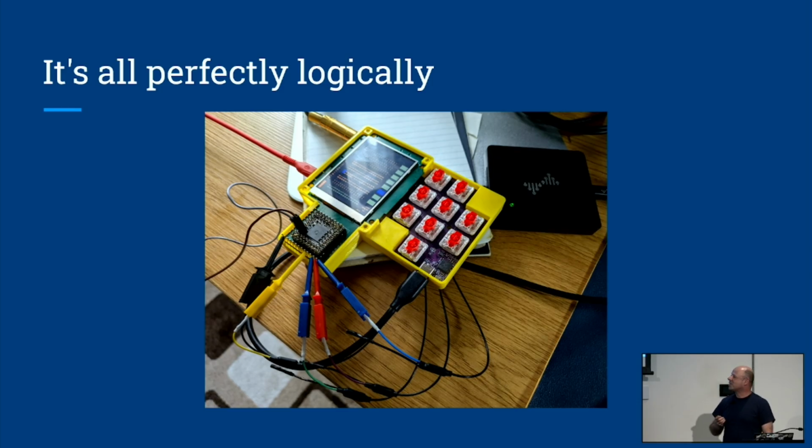Couldn't figure out what was happening, so I finally had to break out the Logic Analyzer, connect up the probes to the various output lines, and realize that my almost infallible colleague had actually just switched two of the wires around, so they weren't as labelled on the original PCB design. Once I knew that, of course, it was super easy to change things around, and it worked perfectly. But I don't think I would have been able to figure that out very easily if I hadn't had a Logic Analyzer to hook up.